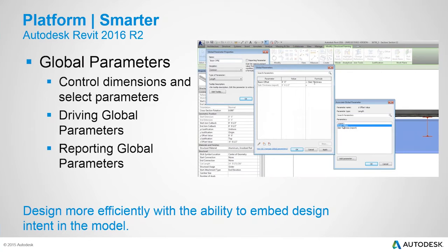In English, for example, previously elements like beams wouldn't naturally adjust within a project just because the floor slab thickness has changed. Now, if you assign a global parameter, you can associate the parameter with the beam so that when the slab thickness changes, the beams can adjust too. So this can be really quite a saving. It's worth applying these in-project global parameters.